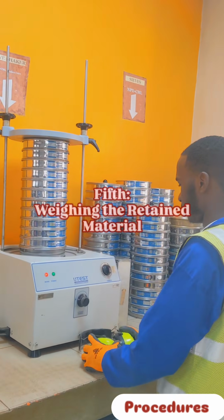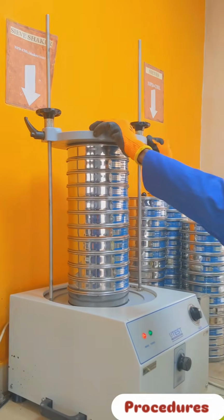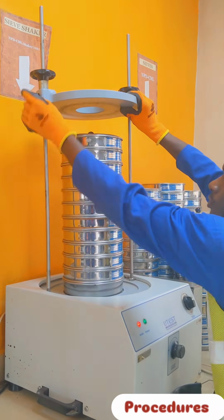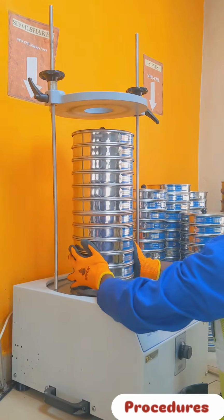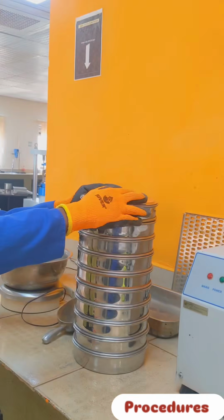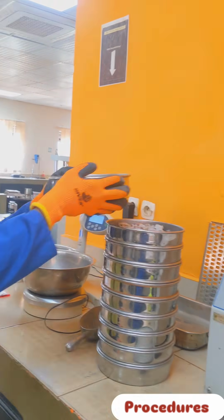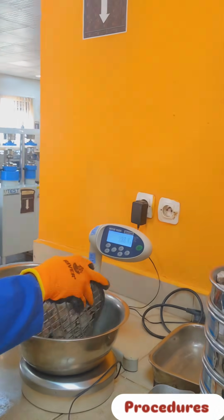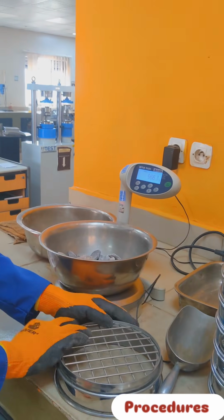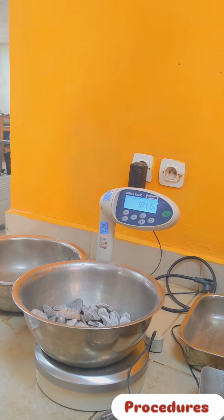The fifth, weighing and recording. Once the recommended minutes are up, switch off the sieve shaker and carefully remove the stacked sieves from the machine. Now empty the material retained on each individual sieve onto your digital balance. Weigh the retained mass for each sieve and immediately record the number on the recording sheet. Let's get the data.